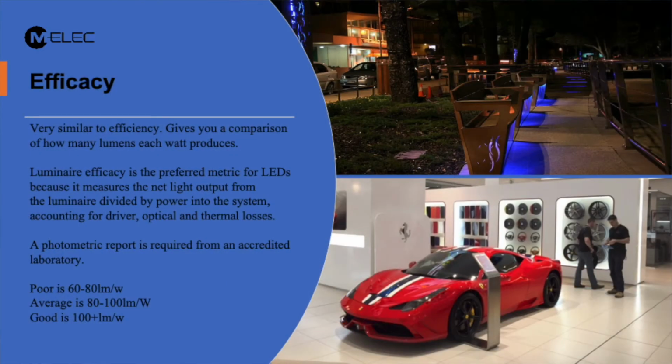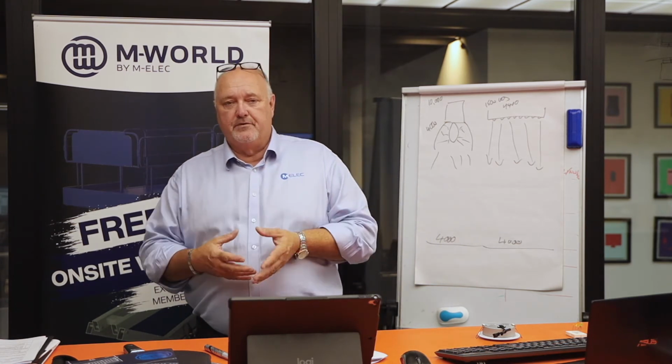We're going to talk now about efficacy, and it's not efficiency spelt incorrectly, but it's very similar to efficiency, right? It gives you a comparison of how many lumens each watt produces, and it's really important because, when we're looking for a quality solid light, like our Knox fittings, you want them to be able to shine up a whole yard, so we're looking at the maximum possible lumens per watt.